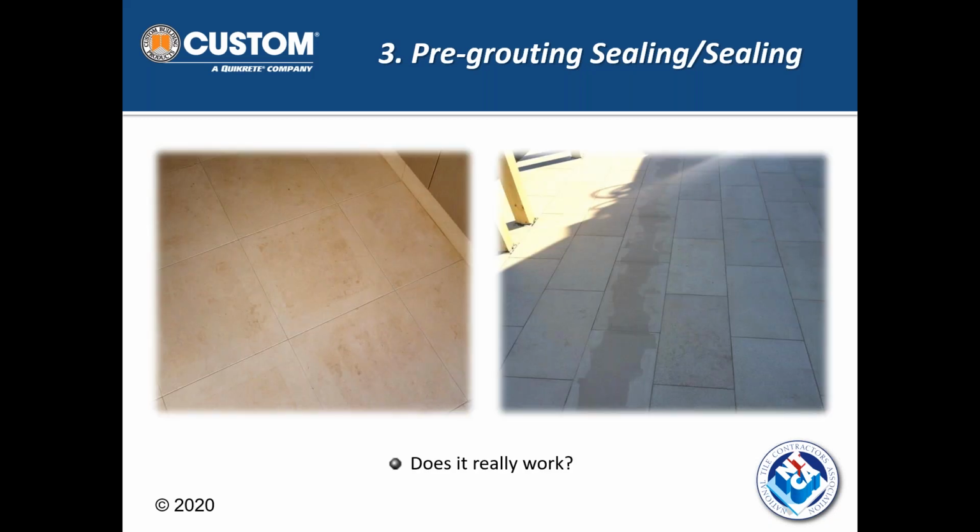So does it really work? Again, on the picture on the left, sure it works, but it doesn't work if you just take a sponge brush and just seal the edges of the stone and then spread grout over the face of the stone. It worked, but only where they sealed it around the edge. So again, we also have to employ the right techniques. It's not just, well, hey, we did pre-seal the stone. Well, did you pre-seal the entire face of the stone, not just the edges, if you're going to spread grout over the entire face of the job?